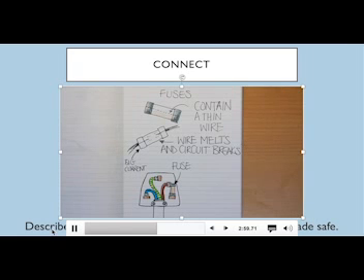A fuse should be connected to the live side of the circuit so that when it blows, any connected appliances become safe. In a plug, the brown live wire should therefore be attached to the fuse. The blue neutral wire should be connected to the other short pin, and the striped green and yellow earth wire is connected to the longer topmost pin.